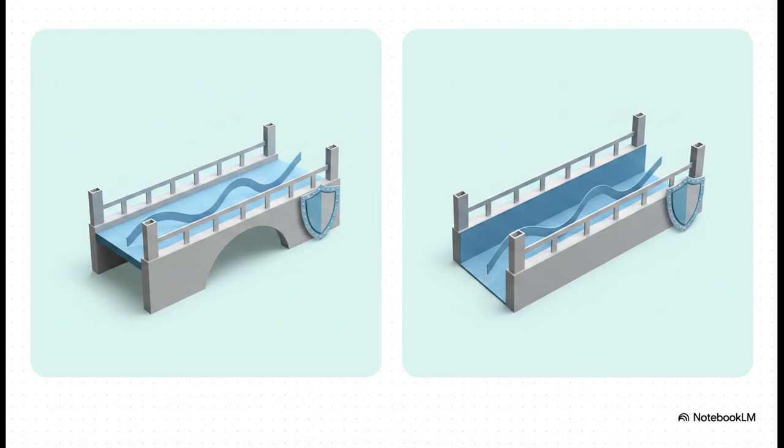And we can actually put a number on that buffer. For a high signal, your noise margin is simply what the speaker promises to deliver, that's VOH min, minus what the listener needs to hear, that's VIH min. Same idea for a low signal. You take the maximum voltage the listener will accept as a low and subtract the maximum voltage the speaker will ever output for a low. The bigger that final number, the more resilient your circuit is going to be.